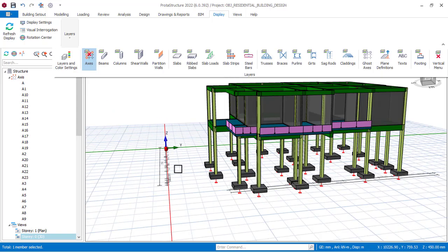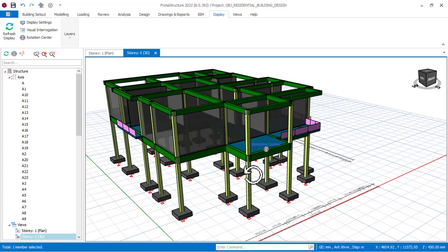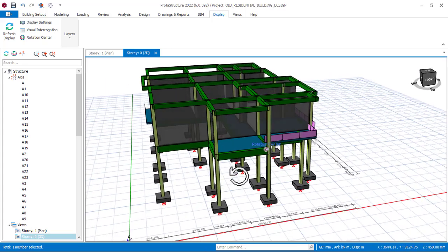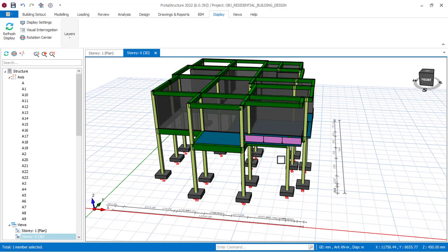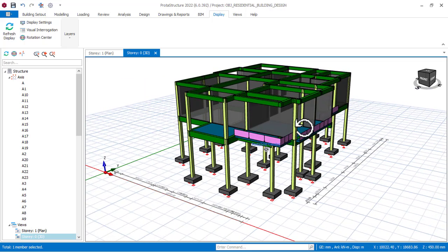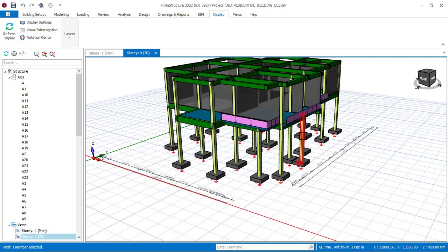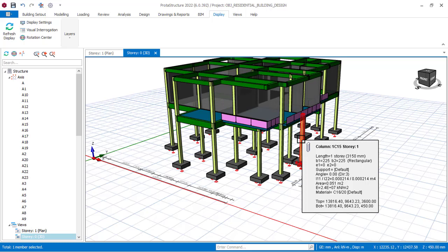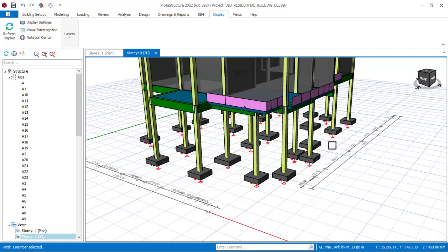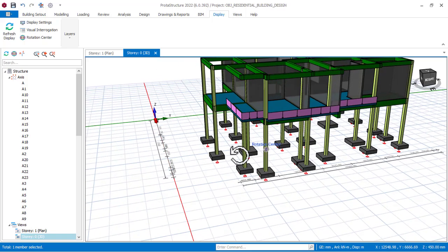So following the steps which I just showed you, you can design a pad foundation perfectly for any kind of structure, depending it is no more than a 4-story building. Most people use pad foundation for a 5-story building. Well, it's fine, but for me, I don't like using it. Although if I'm going to use it, I'll still use a ground beam to connect all the columns together. That will give good stability. So right now, you can see what we have done so far.